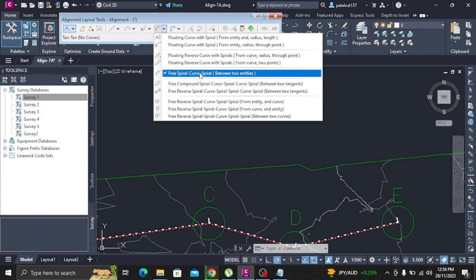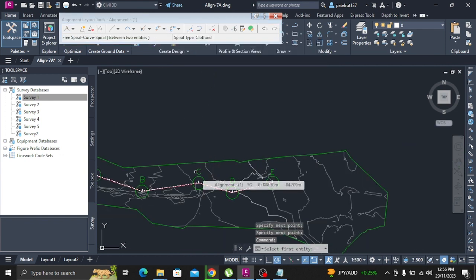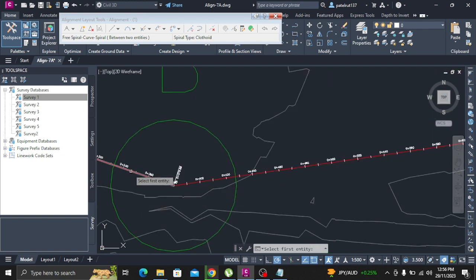In the Alignment Entities vista, in row 2.2, examine the length column. In row 2.2, change the radius value to 200.000 m. Press Enter. In the Alignment Entities vista, select row 4. In the Radius column, change the value to 100.000 m. Press Enter.